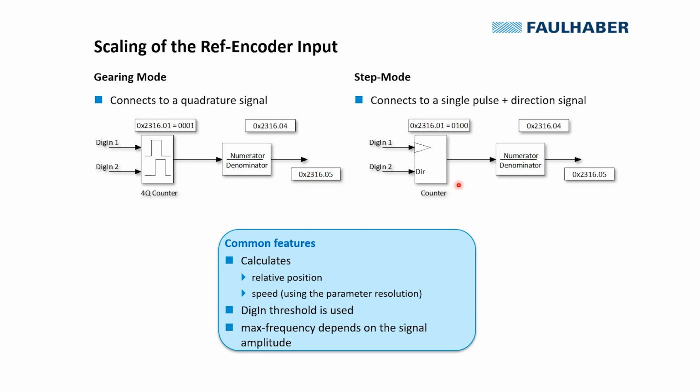Or on the other side here, when it's the single pulse train only used here, it's of course 512 pulses per revolution. And when I want again to use the one-to-one relation, so one turn of my reference, of my dial, to move my motor by one turn, it would be rescaling the 512 external pulses to 4096.